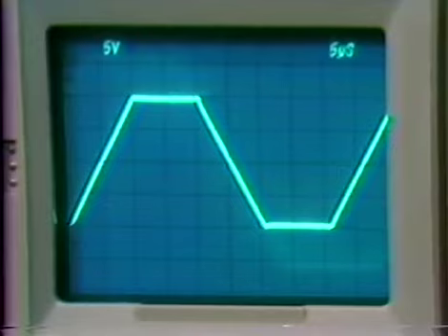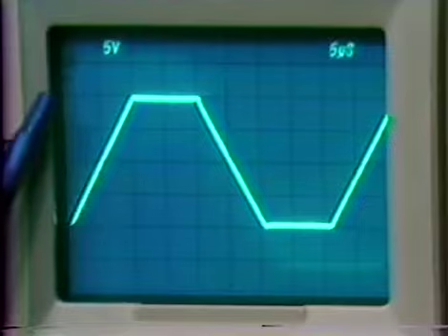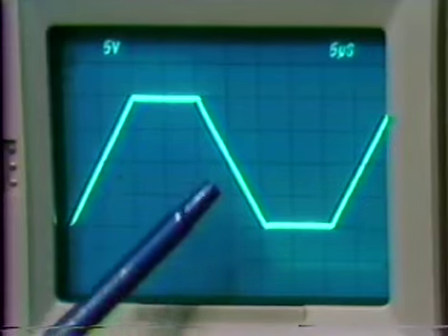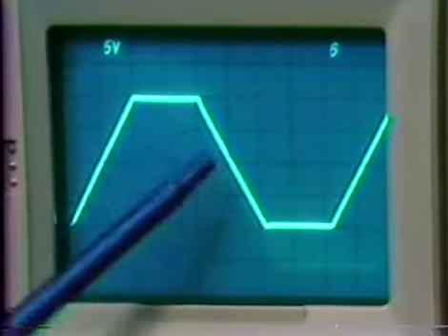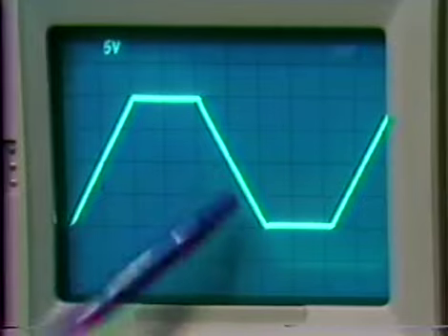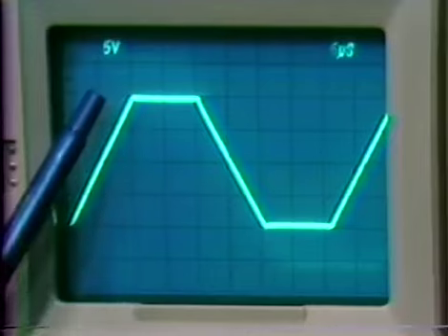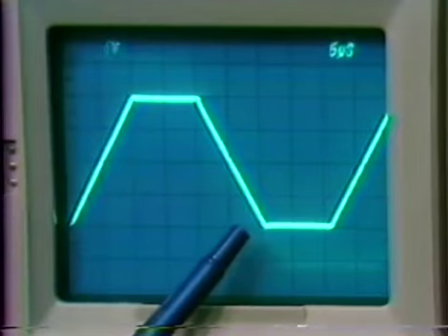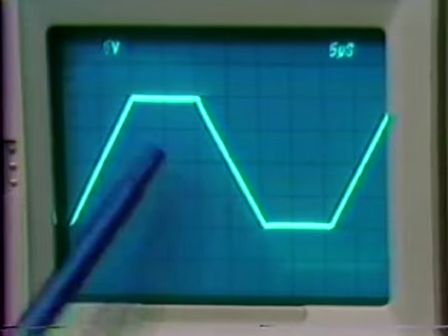If we examine what happens as the amplifier comes out of saturation, we put in a full amplitude step. It takes quite a while to slew. We're at 5 microseconds per division, so these transitions are taking 10 microseconds. We're going through a total 20-volt excursion in 10 microseconds, so the amplifier is slewing at a couple of volts per microsecond. Right in here and right here, the amplifier gets out of limiting and enters its linear region.